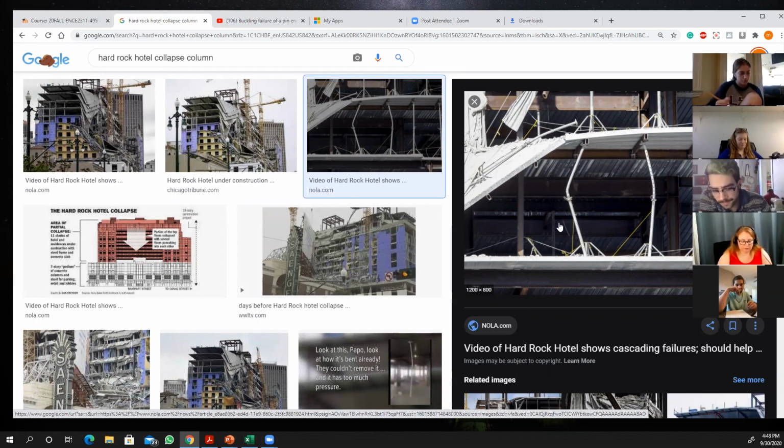What else can I change? Diameter, length, because if I make it shorter, it's going to be more durable, right? So this column buckling is related to the parameters that we can change. We can adjust them to increase the critical load, so that the column I designed can bear more load. It can be optimized, let's put it this way, if it's clear.